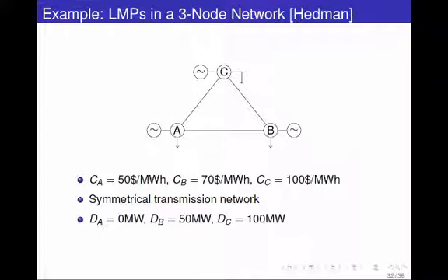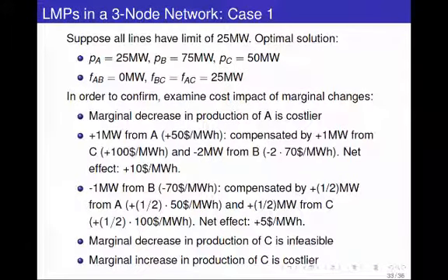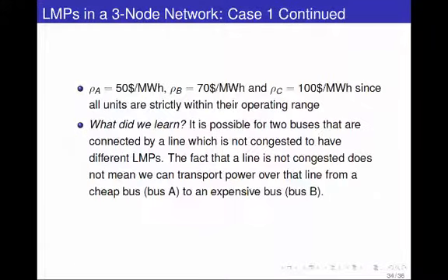So the only interesting other thing to look at is moving B. And it turns out if we go through the numbers that it's more expensive as well. In fact, there's one case here missing, which is moving up B by 1, sorry. But hopefully you get the idea. So all of these proposed changes, if you also account for flow limits, are more expensive. That's how you can prove optimality of the present solution.